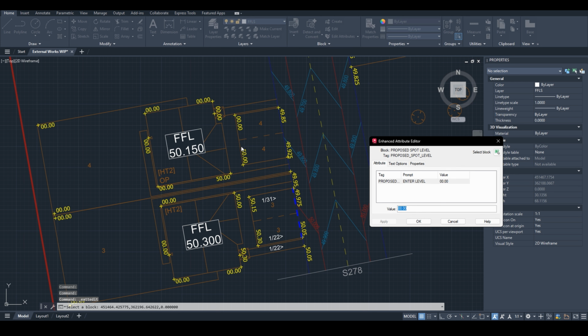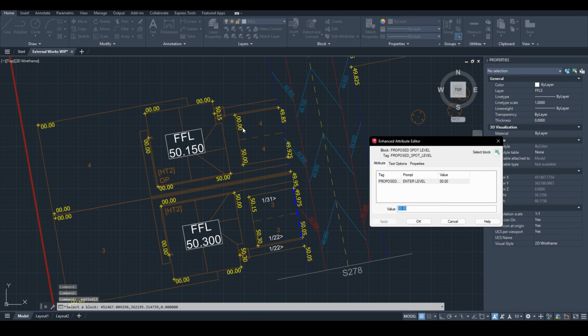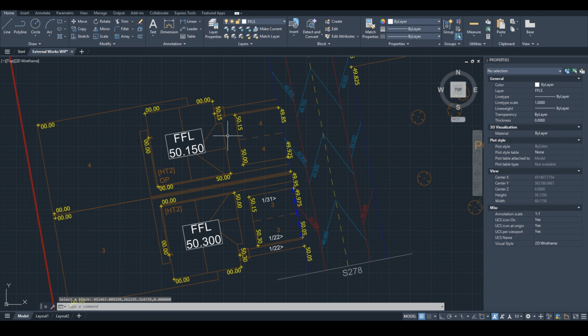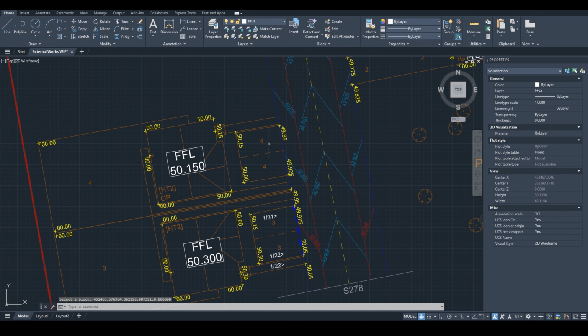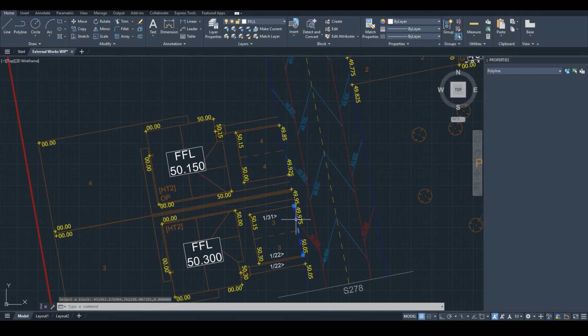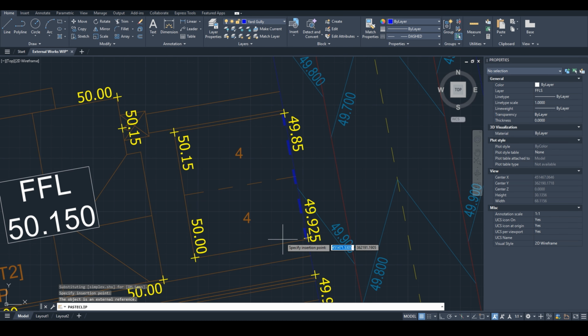Remember, the external level at the front door should be the same as the floor level. Again, to avoid stepping up to the front door, we will have this corner at the same level. For this corner of the plot, as there is nothing going on in the layout here, we can easily bank down 150 mm from the front door to achieve the lower level at the corner of the plot. Just make sure that the 150 mm bank is no steeper than 1 in 3. We will then go ahead and put the drainage and gradient annotation on the parking bays.